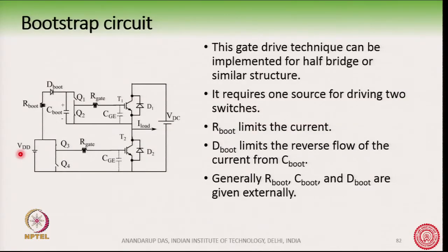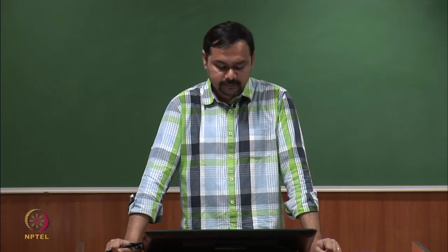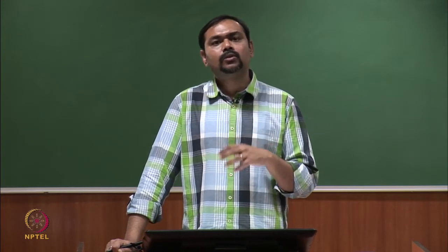Now we will talk about bootstrap circuits. Often, for this kind of voltage source converter, we drive half bridges, and we have seen that we can use gate driver boards for each IGBT, one driver for the high side IGBT and another driver for the low side IGBT.